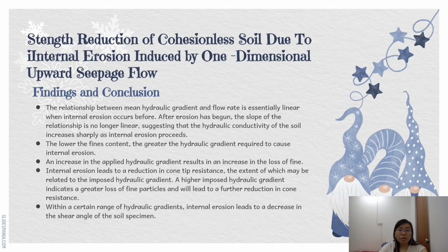The lower the fine content, the greater the hydraulic gradient required to cause internal erosion. An increase in the applied hydraulic gradient results in an increase in the loss of fines.